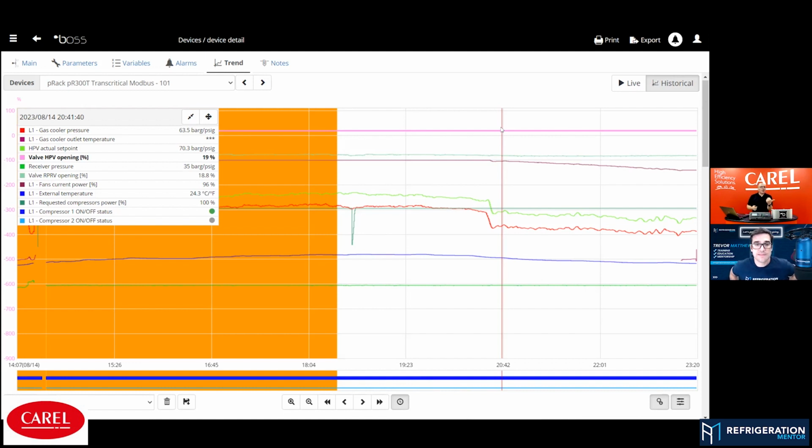So the first thought was maybe we don't have enough refrigerant in our rack, so in our complete application. Could be an issue, maybe. The guys from the service don't have enough CO2 in their car to fill up everything. Could be one part. But what we see, our flash gas valve is working. Even if I don't have the right gas cooler pressure, I have to regulate my flash gas. The flash gas valve has to regulate. So these two informations don't fit together.